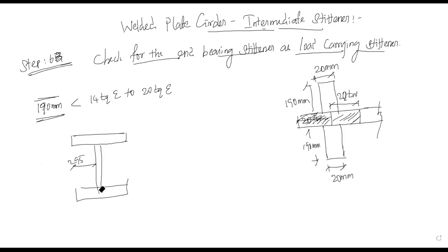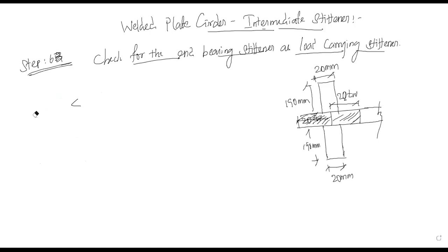So for that we have done one check, which is nothing but check for buckling of stiffener. In the buckling, it is safe, that is P should be less than PD, the design compressive strength of the member. So it is safe to carry the buckling force. Now let us move on to the load carrying capacity, which is nothing but the local capacity of web.